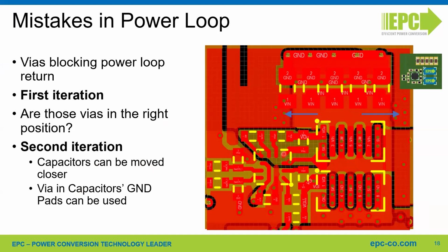So if you have two separated gate drivers, one for the high side and one for the low side, once the input signals are connected properly and they don't pick up noise to both of the single gate drivers, then I don't see any particular issue. And you can use the same rules for this half bridge gate driver example, but you have more flexibility regarding the placement of the two gate drivers.